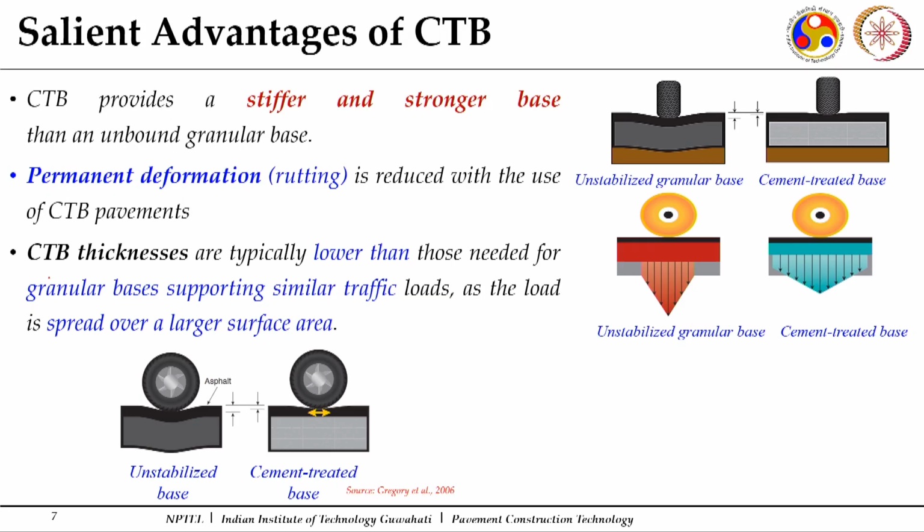So, depending upon the requirements, depending upon the site specific or region specific challenges of the projects, in terms of the design traffic which it is going to carry, we can pick a solution to use a cement treated base course. As I mentioned, cement treated base courses have thickness typically lower than those needed for granular bases supporting similar traffic load, as the load is spread over a larger surface area because of their higher stiffness and strength.